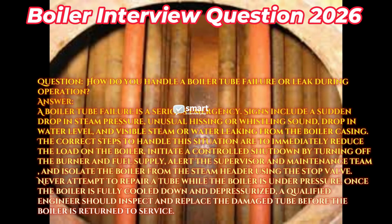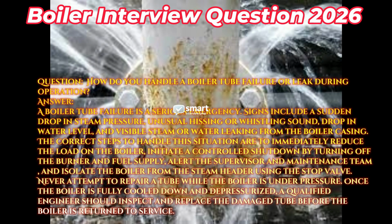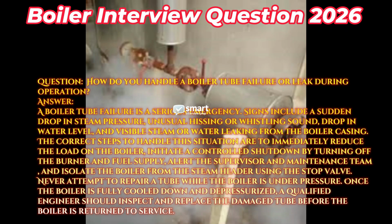Question: how do you handle a boiler tube failure or leak during operation? Answer: a boiler tube failure is a serious emergency. Signs include a sudden drop in steam pressure, unusual hissing or whistling sound, drop in water level, and visible steam or water leaking from the boiler casing.